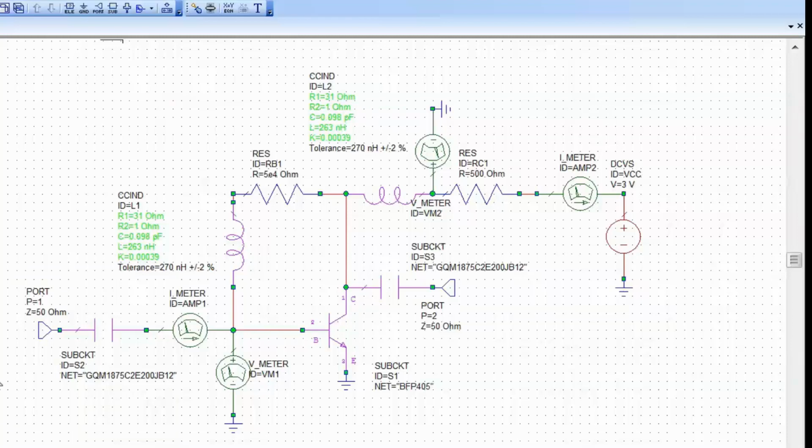The important thing was biasing the transistor correctly and also choosing the right components to isolate DC and RF. And now we can represent our S parameters whichever way we like. We are used to representing S11 on a Smith chart, but in this case, because subsequently we will be using equations which require numerical data, it would be advisable to have our results in a tabular form.